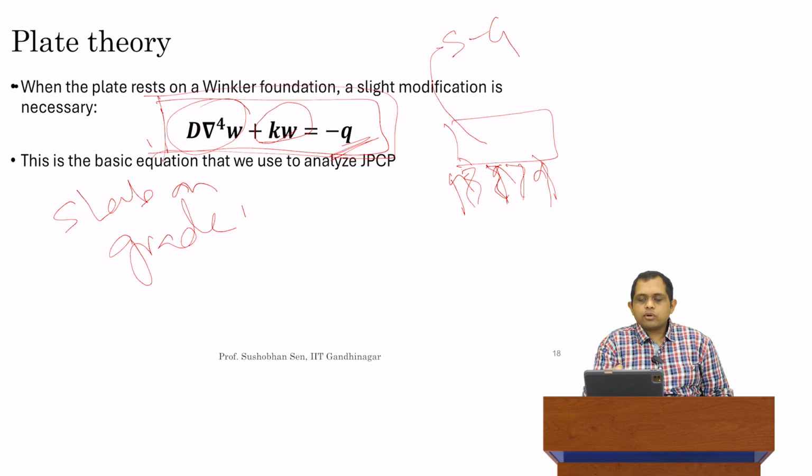One thing you may note, which we'll also come back to in subsequent lectures, is this is a differential equation. When we are solving differential equations, we typically also require boundary conditions, at least when we're solving boundary value problems. Now, the reason we require boundary conditions is we basically need to make sure that we have a unique solution. So what would happen is if I did not have this Winkler foundation, and if I loaded my plate, then my plate would just fall through the ground basically. There's nothing to prevent it from falling. In other words, there's nothing to prevent it from having rigid body motion. So the purpose of providing any boundary conditions is to prevent rigid body motion from happening.